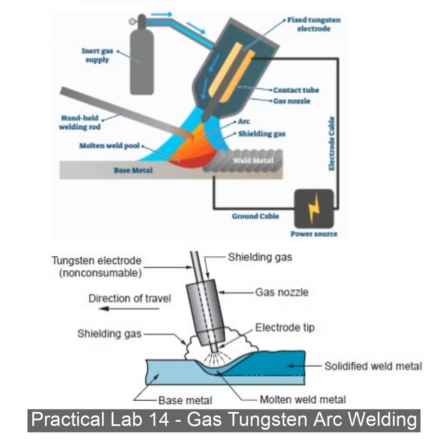The shielding gas is used to protect the workpieces and the molten base metal from the environment. Shielding gas is normally argon gas. We can use helium gas, but in the NED fabrication lab we use argon gas to perform this welding process.